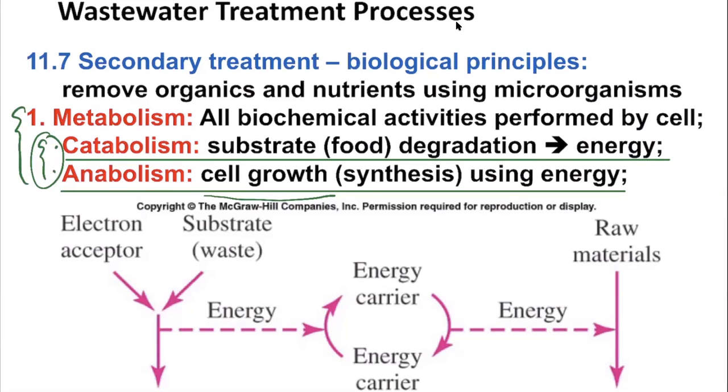So let's imagine if we just put in hundreds of bacteria. If they can propagate into millions in a time period of hours, right? That's going to boost up the BOD consumption much faster. But at the same time, we want these bacteria to consume food, right? Just based on itself, not basically using all of the energy to propagate, but also to consume these organics. Okay.